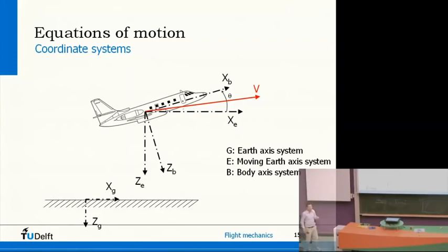And the most commonly made mistake is that you think that the airplane is following its nose. It isn't. This airplane, as it is oriented now, could actually be dropping out of the sky like this. Then the airspeed vector would be pointing downwards.